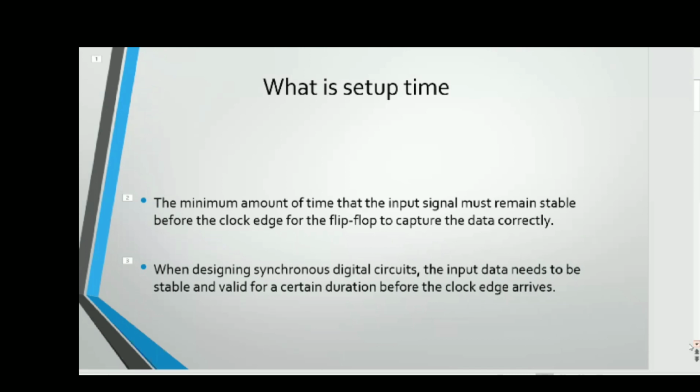So friends, setup time is the amount of time that the input signal must remain stable before the clock edge of the flop to capture the data correctly. So this is the definition for the setup time. So it is the amount of time the input signal must remain stable before the clock.